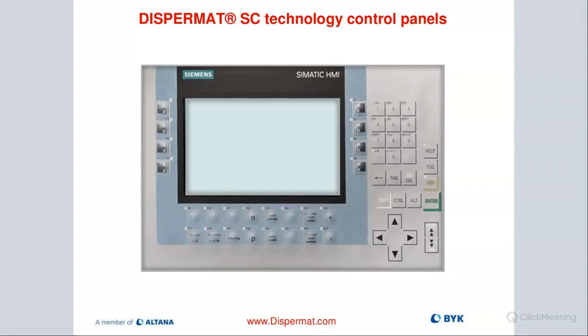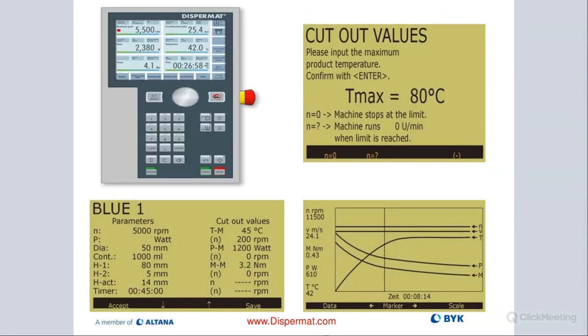And if you like to integrate a scale, for example, and weigh all the material right on the machine, because you can actually put the machine on a load cell, then that would help you there. And then you basically have all the critical information, raw material information, loading, and so on, as well as all your dispersing and milling parameters on this HMI control panel. Siemens makes those. Unfortunately, right now, they have really long lead times, and I think it's like 10 months now for that control